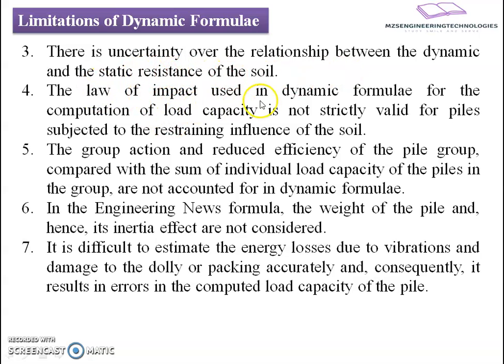The law of impact used in the dynamic formula for the computation of load capacity is not strictly valid for piles subjected to the restraining influence of the soil. Theoretically it is good, but when it is actually implemented, we can't say there is a direct relation. Such a direct relation we can have with reference to the soil and its character.